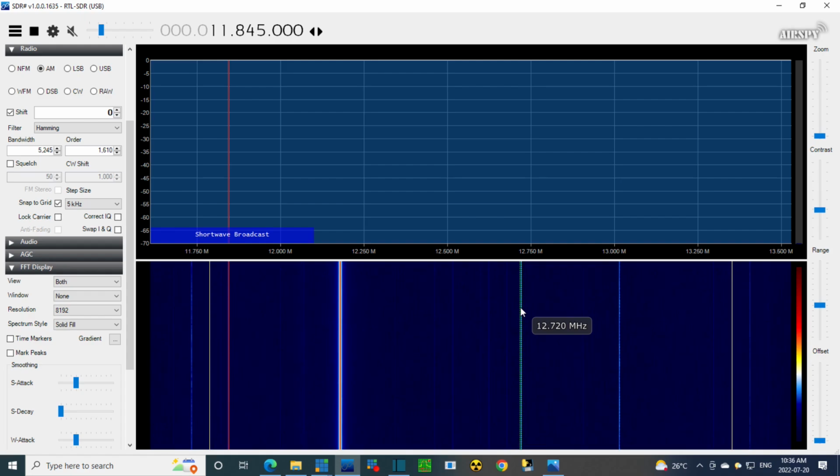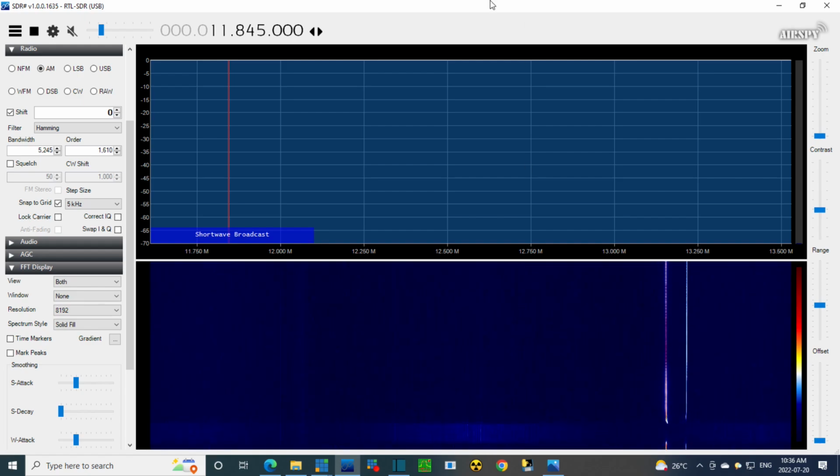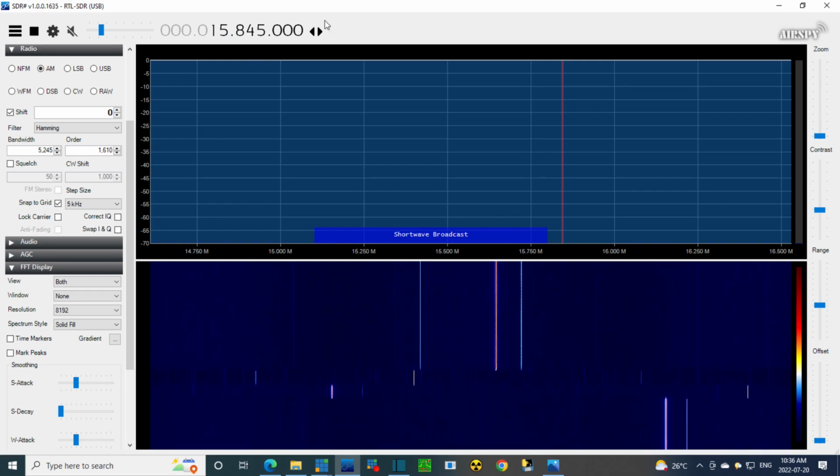Next band. Okay, so this is the 15 megahertz band. This is the one where we saw virtually no voltage developing on the grid. So 15 megahertz here. We're not really making our discoveries in the way I would have hoped. But this can lead to an elimination of a potential problem. The problem being a weak local oscillator.